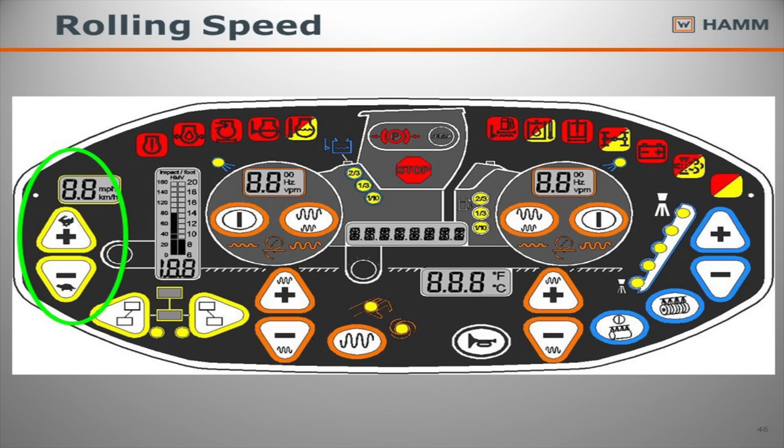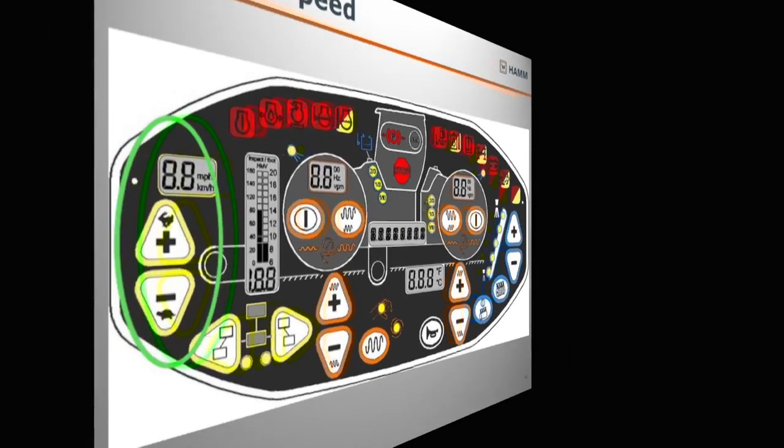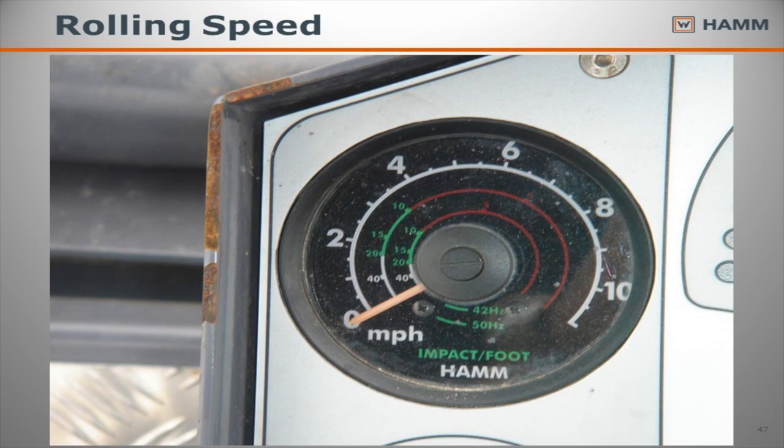The other thing, like I talked about, maintaining that proper impact spacing is consistent speed. Most all rollers now have a set speed, so no matter how far forward you put the lever or backwards, you maintain the same speed. Now you maintain the same impact spacing forward and backwards on your pass, so you get consistent impact spacing for every pass you do. You should get more consistent compaction. Older rollers, you were trying to control your speed with the levers, so you had an accordion effect of that impact spacing going down, so it would vary your compaction effort.